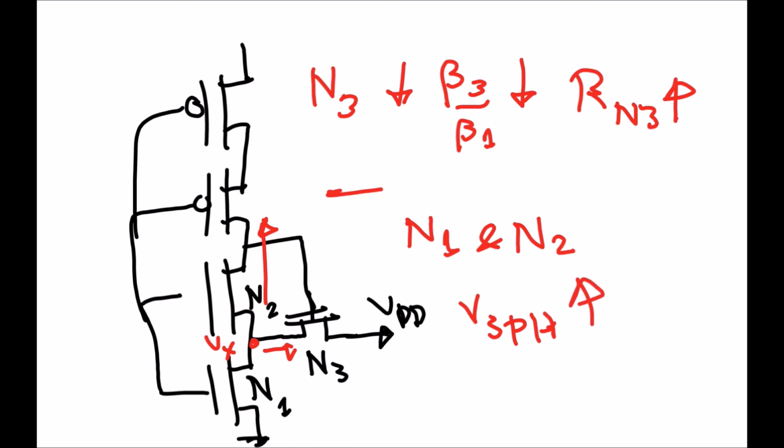It's important to notice that for the CMOS inverter, the current conducts early in N1 and N2. This is charging the output capacitance slowly. For the Schmitt trigger, we have current passing through N3, and it usually takes a while until N3 is on, and the current is higher than its counterpart in the case of the inverter. This causes the switching to be faster.